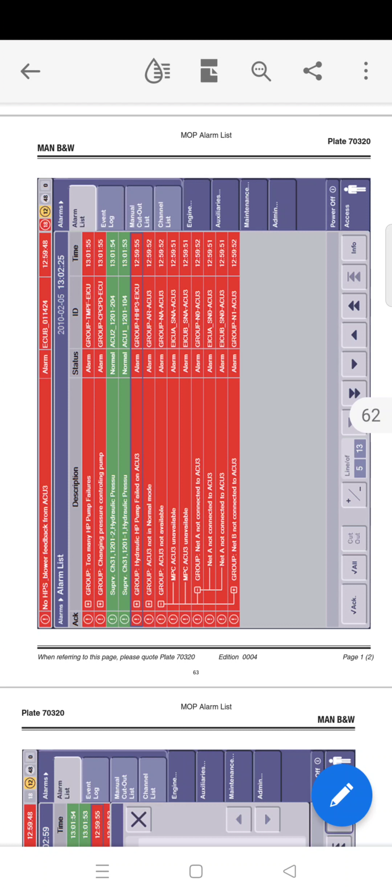So an alarm can only appear as one line in the alarm list. An acknowledged alarm going into normal, or an alarm changed to normal being acknowledged, is immediately removed from the list. So the alarms which have already become normal will be removed from this list. Acknowledgement of a single or all alarms is allowed on both levels.